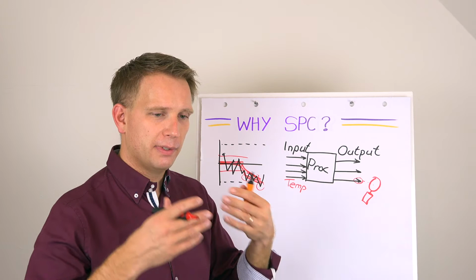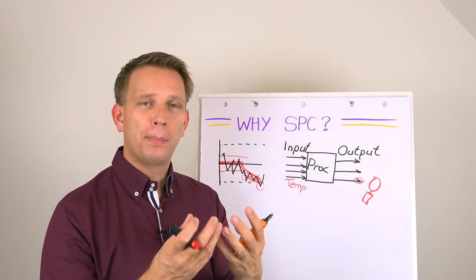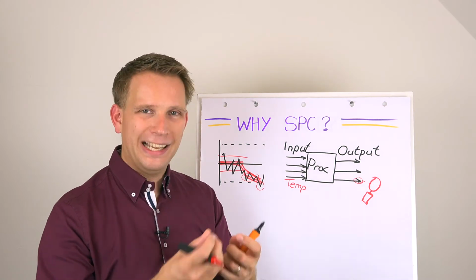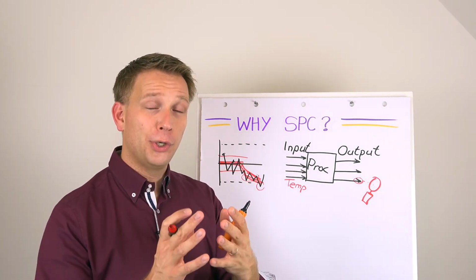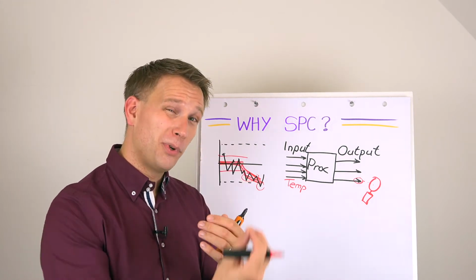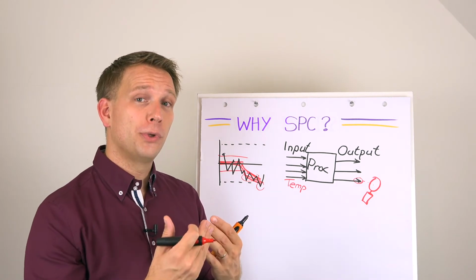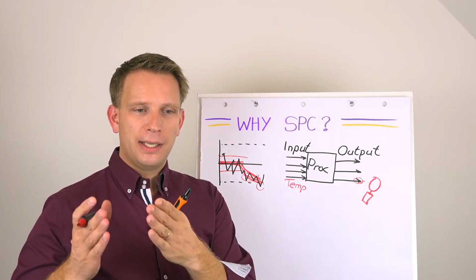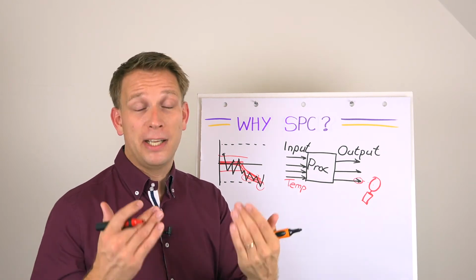It's quite often even steam that you're pushing in. But if there is sediment on the plates, so if there is calcium or other stone on the plates, it gets dirty. Or on the product side, some of the product has made a film on your heat exchanger plates, the heat transfer will not be as good. And you will see that the delta of the temperatures going in and out changes, it becomes less.